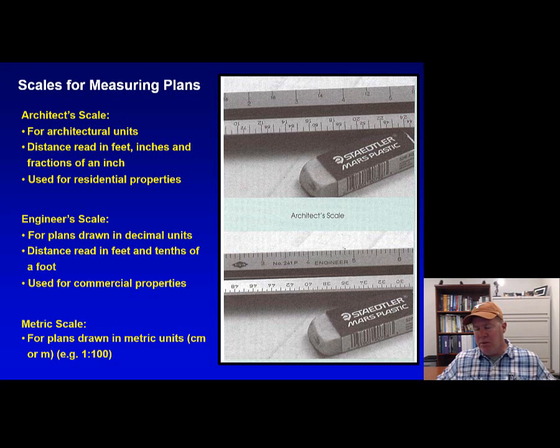Good thing with us, and what I tell my students, I always try to tell them, estimate just a little bit higher. If something's 29.5 feet, go ahead and say 30. You want to give yourself that margin of error. And when it comes to lengths of irrigation pipe, if it's 6 more inches or 2 feet more, you're not going to lose the job based on that.